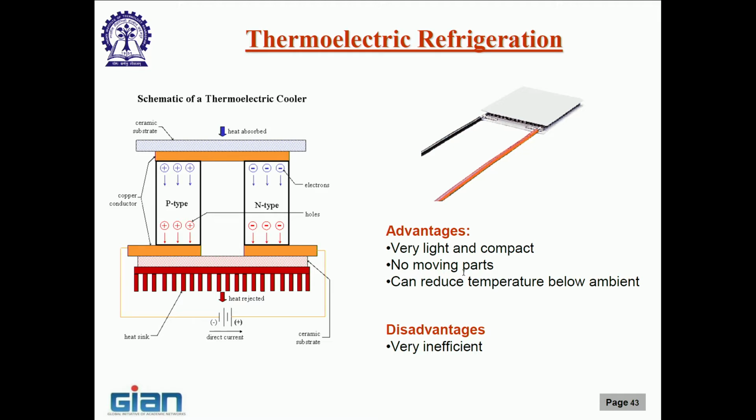The Seebeck effect says that if you have two dissimilar materials connected at two ends, and you have a temperature difference, you are going to give rise to an EMF, and therefore there will be a current flow and you can measure a voltage across it. That is the Seebeck effect, and that is the principle of operation of any thermocouple.